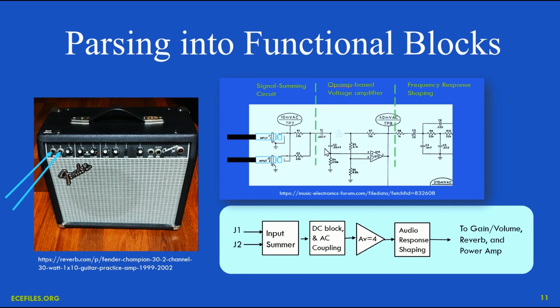And that's really important in design and understanding of circuits. As we'll see today, the amplifier here in the middle has what's called an output impedance, which is close to 0 ohms, so it can drive into this next circuitry and not be affected by its connection to it. This next circuitry here after the amplifier section will not load the amplifier significantly. So instead of trying to solve this complicated looking circuit with Kirchhoff's laws and nodal analysis and whatnot, we've broken it down into simpler pieces, and that's how engineering is done. Things are broken into subsections, or sometimes called subsystems.